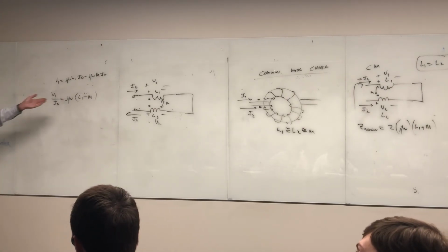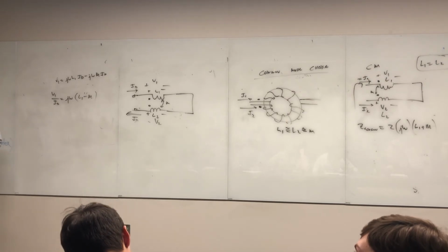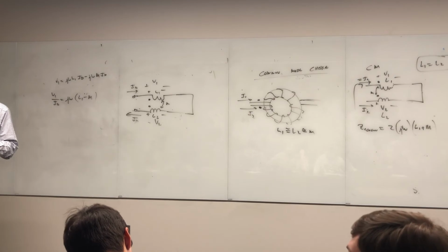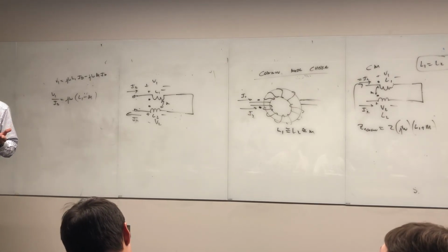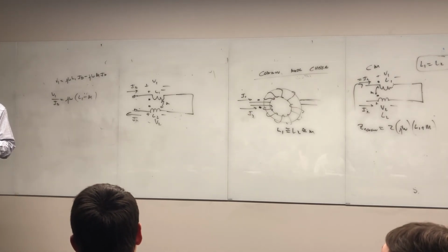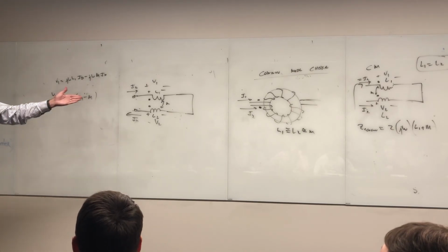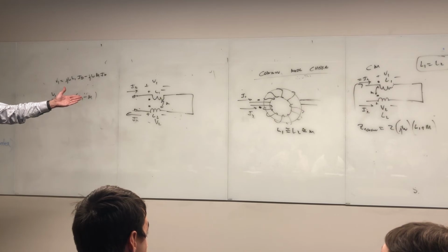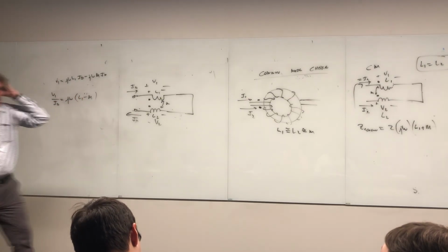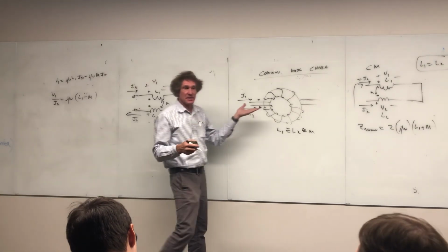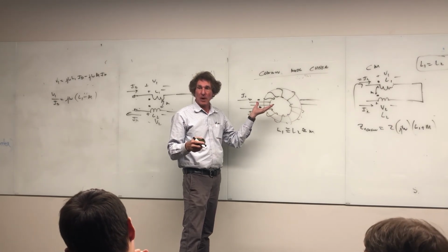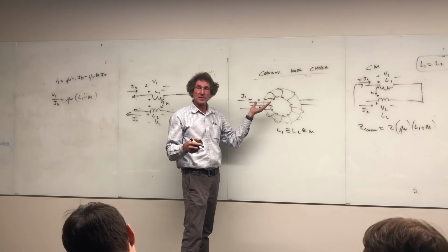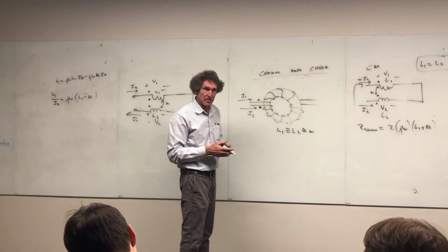If M is about equal to L1, if they're within, say, 0.1%, 0.2%, then effectively what you've got there is a zero impedance to the differential current. And where is the impedance going to occur? It's when it's common mode currents. It's going to stop that. And that's the idea of this whole thing. When you do it this way, this little device right here is an amazing deterrent to common mode currents, and it's cheap to make. Now the problem with this in the real world is this.